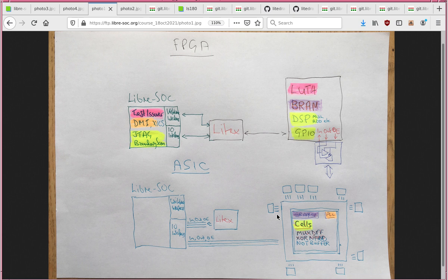So this is why there is a huge amount of interest in NDA-free cell libraries and NDA-free foundry processes, in particular MOSIS. But MOSIS comes with some punishment in that it is double the size of the optimized cells that are not NDA-free, and only some foundries will accept MOSIS formatted GDS2 files. So it's a tiptoeing nightmare, to be honest.